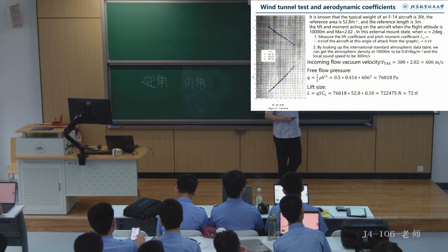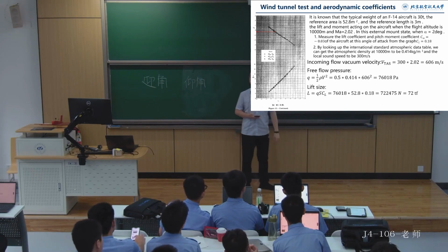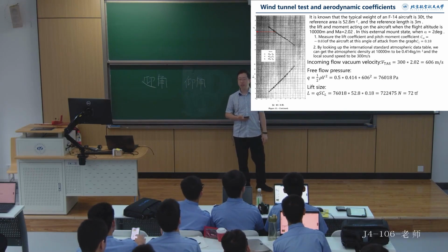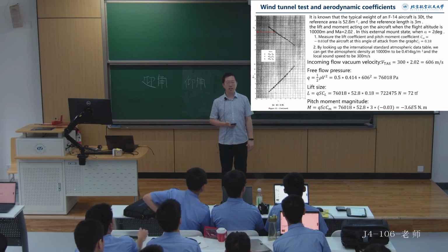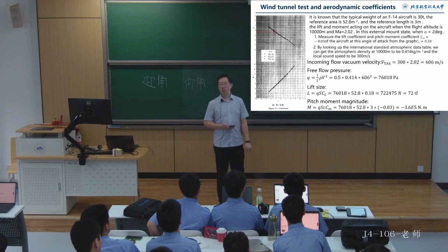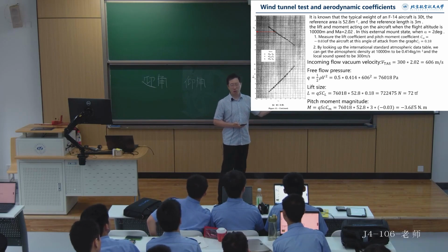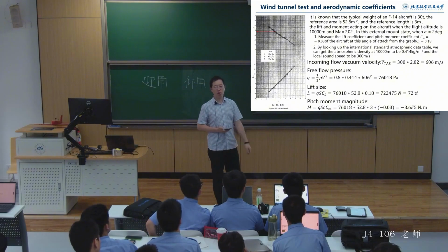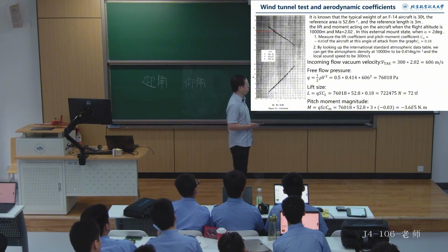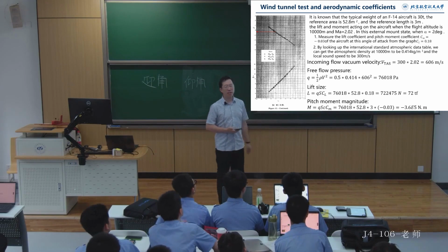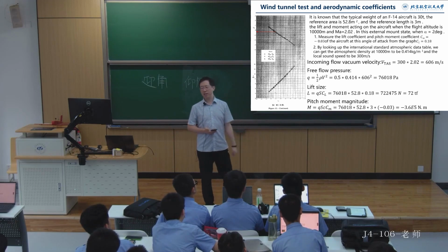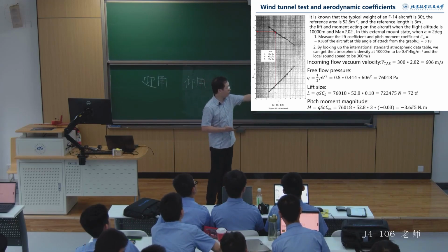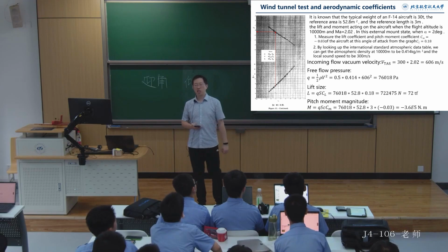What is the relationship when converting from newtons to kilograms? So the local weight. Divide by the acceleration due to gravity, right? What should the approximation be? For approximations, at this level, using 10 is already precise enough, so we should divide by 10, right? Then this corresponds to kilogram force, and then we divide it by 1,000 to get ton force. So, at this point, what do we see as its lift? 72 ton force, right?